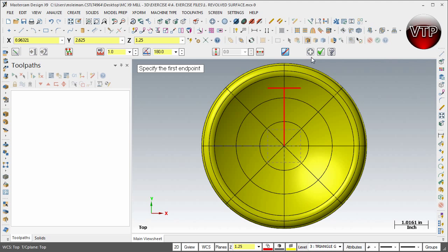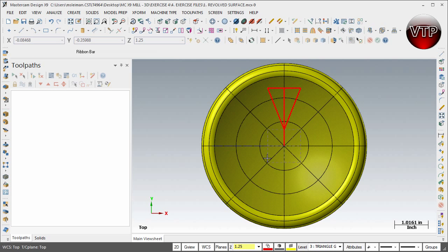There you go. Hit apply, and last but not least, we're going to connect this endpoint to this one right here, and then this endpoint to this one right here. Hit apply and OK. Now we have a few things to delete. First, select this one and hit the delete button. Select this one, hit the delete button, and then there's also one over here on the right side, because remember we created one from here to here before we created one from here to here. So come over here until you see the dashed line only to the right side, select it, it will become yellow, and delete it. So now you should have 3 little geometries.